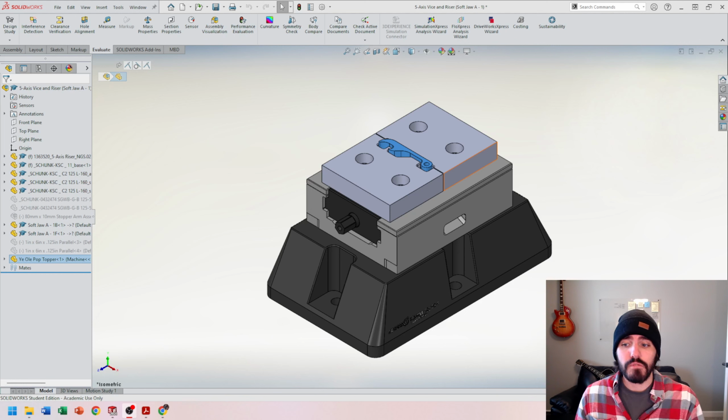And a good example would be a pulley wheel. So a pulley wheel is going to have multiple different operations. It's going to actually go through multiple different machines, and it's going to start off with a turned blank coming out of a lathe. And that turned blank might have a center bore, might have some bearing geometry, and then a specific diameter for the outer dimensions, and then probably some grooves for the belt itself.